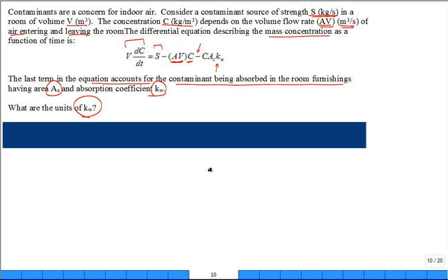So what do we got? A lot of people said it was meters per second, SI unit, right? How did you determine it? Who got the answer first? You two. How did you do it? So basically you can use dimensional homogeneity, and you know that this group has to have the same units as that group, and that group. They all have to have the same units. The most simple one is S by itself because I told you in the problem statement what the units of S are. So each of those groups have to be that.